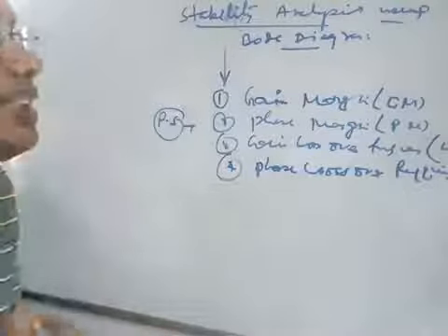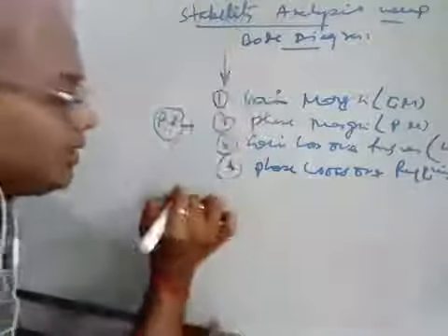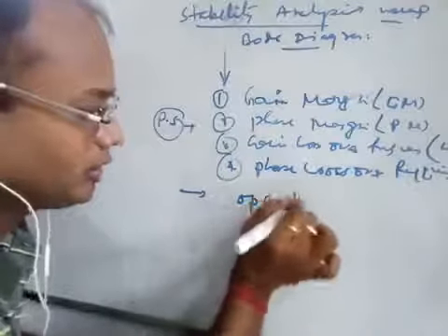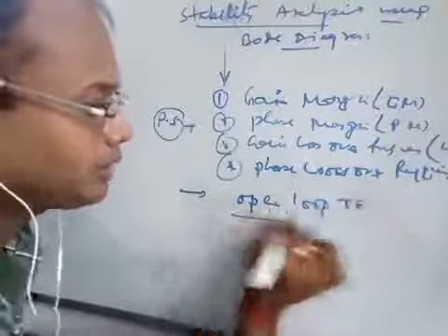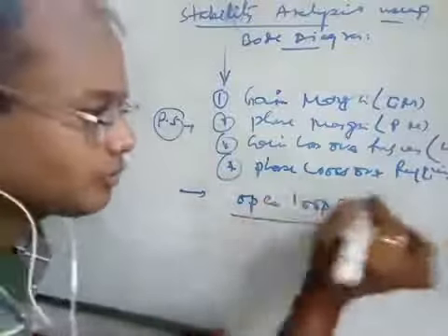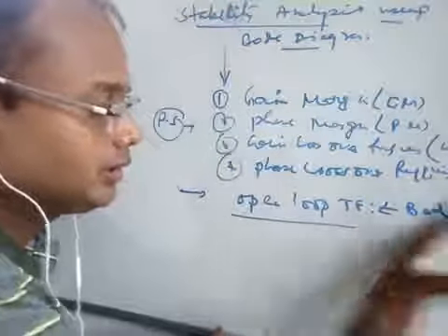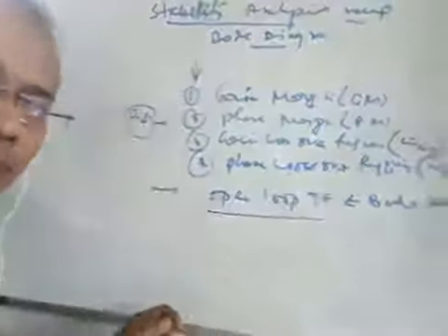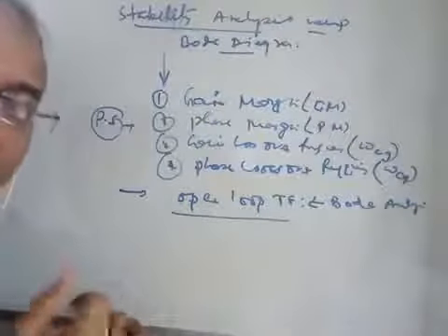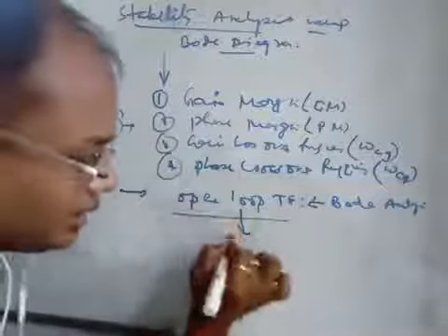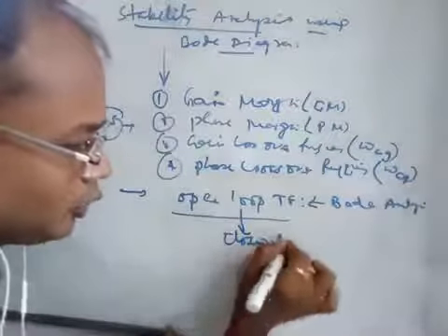One of the important issues is that by using the Bode diagram, we have taken the open loop transfer function. See, the beauty of the frequency domain analysis is that the open loop transfer function is considered in Bode analysis, right? But once you find all these 4 parameters and their corresponding range of values by which the system can be stable, we can say from the open loop transfer function analysis whether the system is closed loop stable or not.